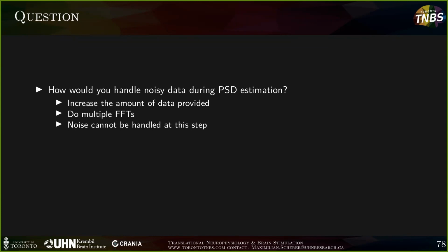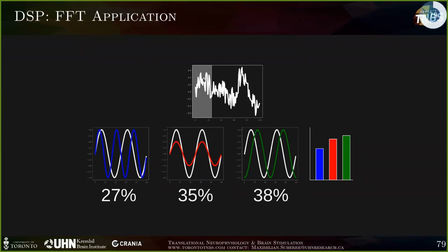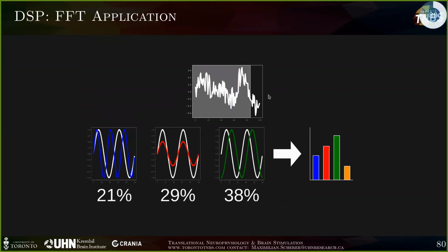So I'm going to provide the resolution to the enigma now. What happens if we just increase the amount of data provided to our FFT? We provide the FFT with more data. And since the FFT is a perfect transformation from time domain space into frequency domain space, it cannot lose information. Since we forced more data into it, it is going to provide us with more output. It's not going to be a higher quality output. It's just going to be more quantity.